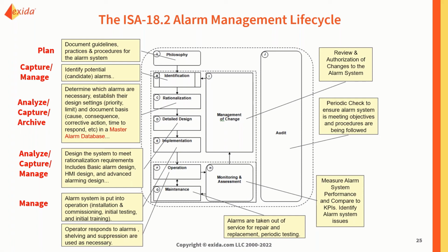Unless something goes wrong, then there would be some kind of problem within your control system when you try to upload this information back to the control system. And there, I actually met some situations where the master alarm database was missing some of the attributes, like your corrective actions for the operator, when they tried to upload that back to the control system, and that creates a lot of problems.